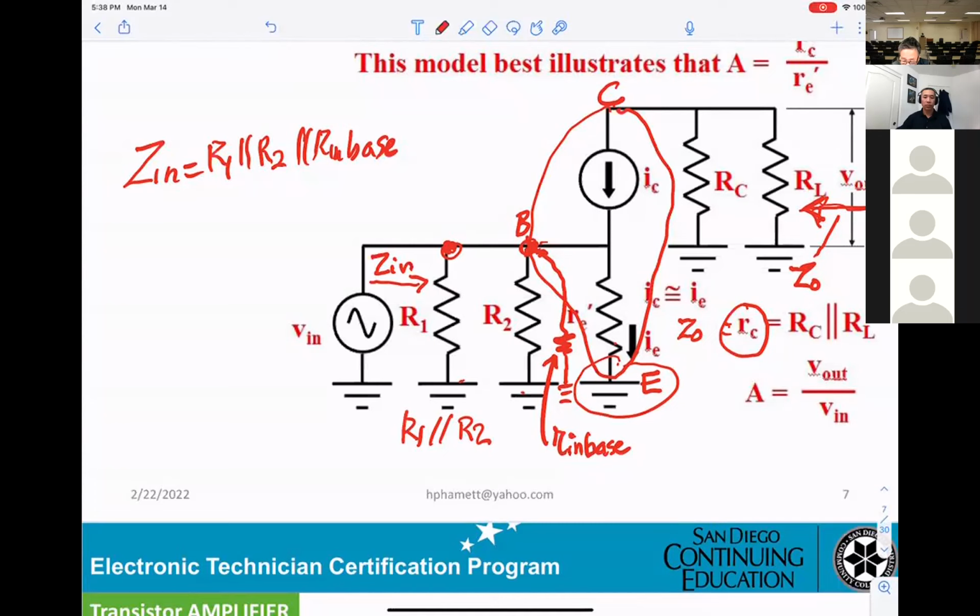In this case, you see RC and RL in parallel. So that's the output impedance. Some textbooks use RC but with lowercase, which means for the AC. Same thing with output impedance, it is calculated by RC parallel RL. That is easy to recognize.